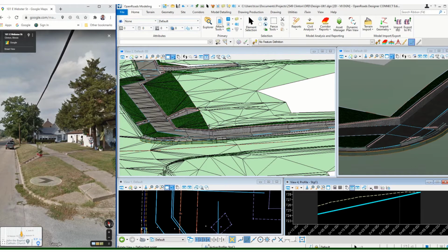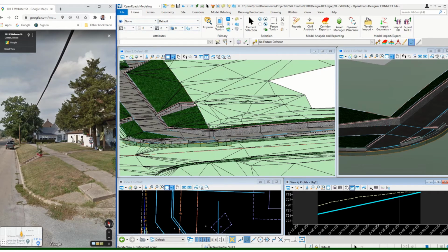And so we went up at a slope of 33%, or a 1 to 3 over 3 foot, which is fine. And then we will not need a curb or retaining wall or anything on the roadside. So just to get tied in with the sidewalk there. And then, of course, the cross slope of the sidewalk is going to be 1.5%. And then we put a 6-inch curb on the back of the sidewalk.